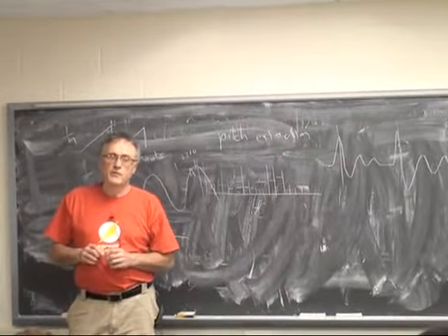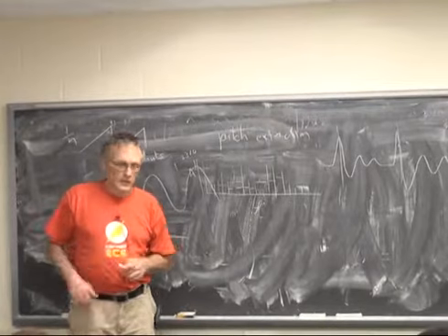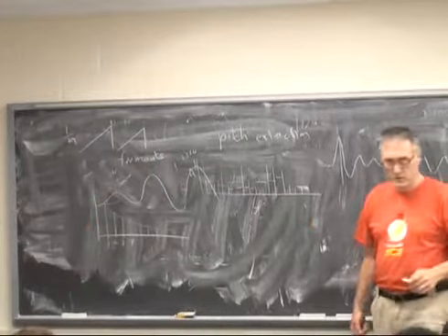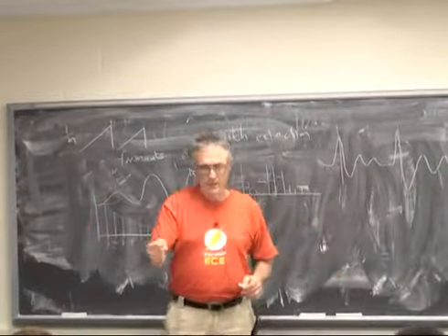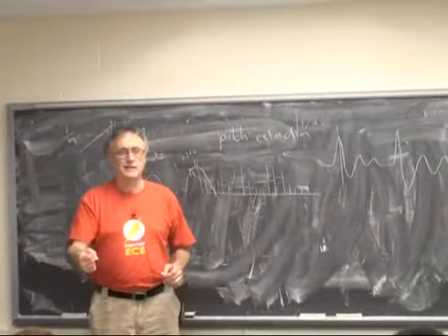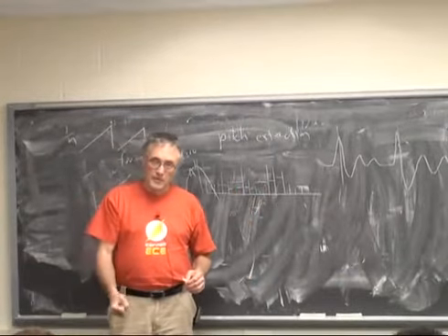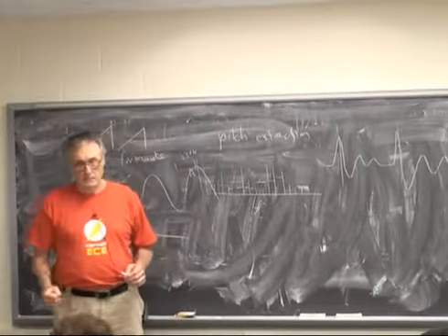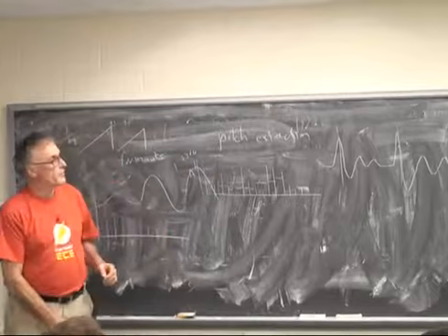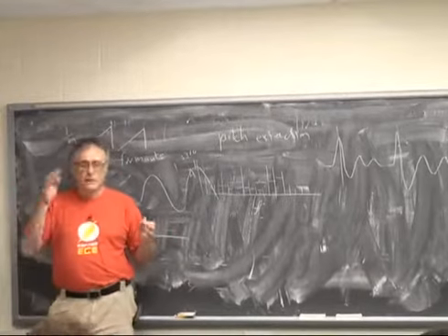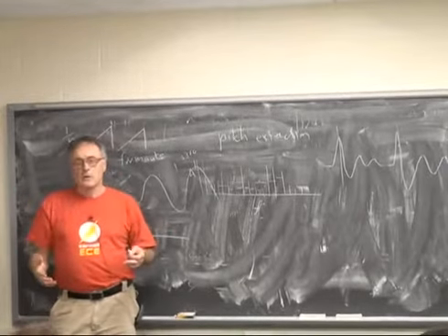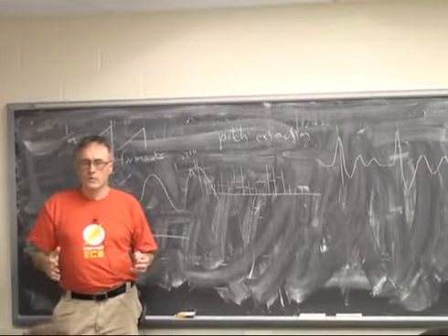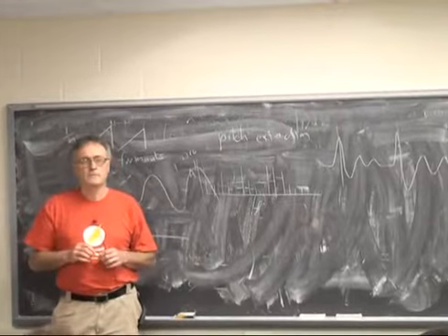Unless you have a very short-term goal, like figuring out how far you're walking from heel strikes, which some pedometers do. The heel strike is a big acceleration that allows you to reset the integration on every step, so you don't get too much drift in that 1 second or so between steps. If you can have a reset signal routinely, then you can probably do it. Otherwise, it's very qualitative. But what do you want to do with the position sensing?